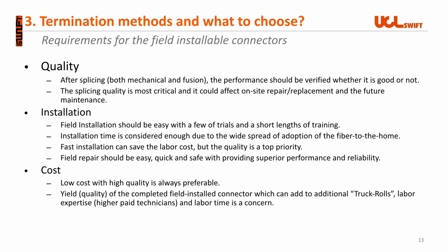Requirements for the field installable connectors. Obviously, quality is a top priority. After splicing, both mechanical and fusion, the optical performance should be verified, whether it is good or not. The insertion loss and return loss should be critical factors, and these could affect on-site repair, replacement, and future maintenance. Installation should be easy, with a few trials and short lengths of training, and installation time is also considered enough for widespread adoption of the fiber to the home.